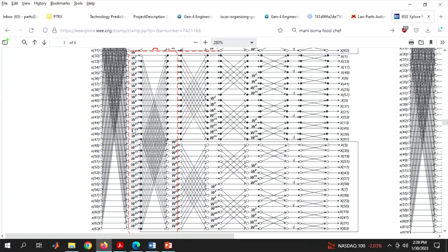So what is the number of complex multiplications here? That's n by 2 minus 2 in the first stage. Second stage, let's look at the bottom part. Now what we are seeing, instead of having n by 2 lumped together, is that we still have n by 2, but they are in two different places: the bottom of the bottom half and the bottom of the top half.